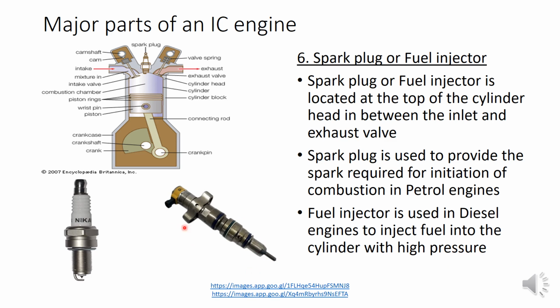So it does not have any function with the spark or ignition. What the fuel injector does is, it has a nozzle here, and with very high pressure it will inject the diesel in an atomized form into the cylinder. So both of these help to initiate combustion in a different way.